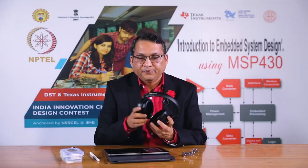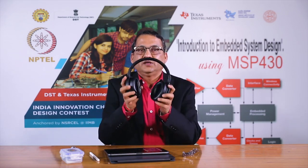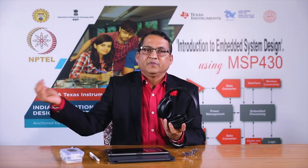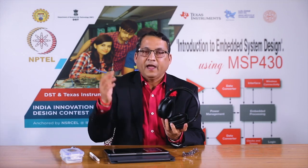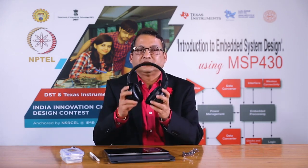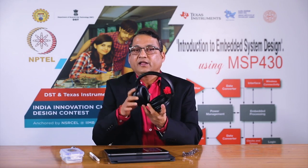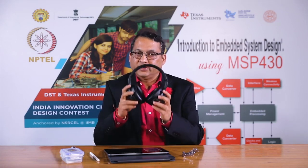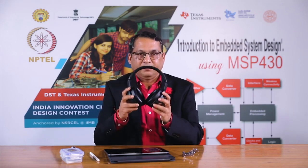enters your ears. This noise cancelling headphone samples that sound, produces an anti-phase version of that sound and mixes it into the speakers in these cups, so that you are actually hearing three sounds: the music that you are playing, the external sound that is leaking through the cups and entering your ears, and the anti-phase version that this headphone is creating. That anti-phase version cancels the noise coming from outside, and you hear only the music that you are playing. And so, it gives a great example of an embedded system.